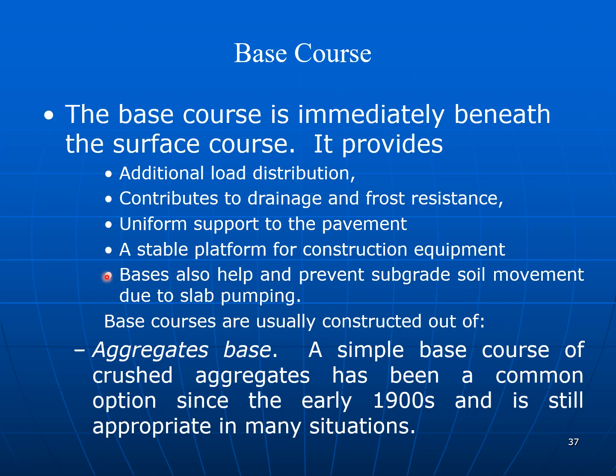Bases also help prevent subgrade soil movement due to slab pumping. Base courses are usually constructed out of aggregate base. A simple base course of crushed aggregate has been a common option since the early 1900s and is still appropriate in many situations.